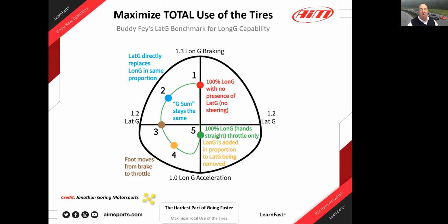So basically, when you're accelerating, and then you hit the brakes, and all of a sudden, this is looking down at something hanging from the rear view mirror. This is the front of the car. This is the back of the car. This is the left of the car. This is right of the car. But the whole idea is we're accelerating, and then bang, we get to a maximum longitudinal reading, and then we blend the end of braking into maximum cornering.